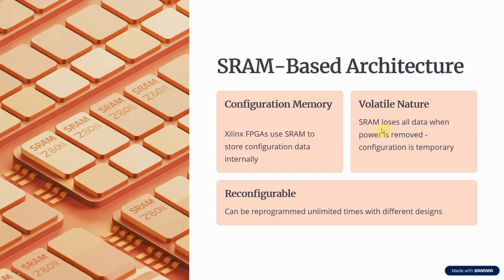Basically, this FPGA is reconfigurable and can be reprogrammed unlimited times with different designs. Using this bit file and the reconfigurability concept, you can reconfigure your FPGA n number of times. If you want, you can reprogram it that many times by generating the bit file and loading that bit file into the FPGA, I mean into the SRAMs.